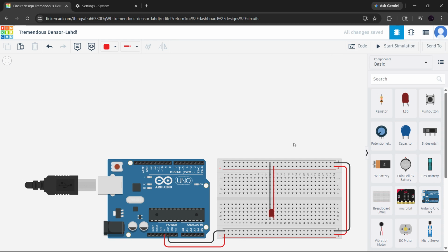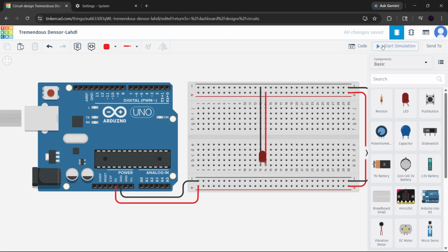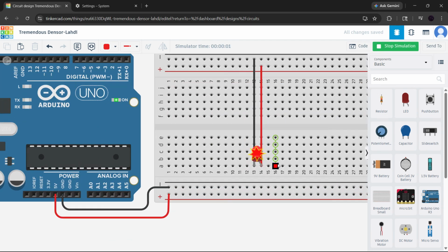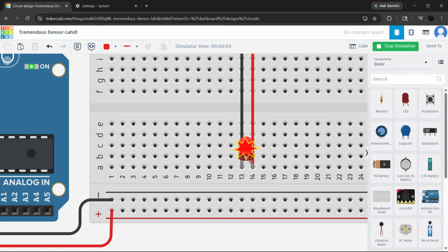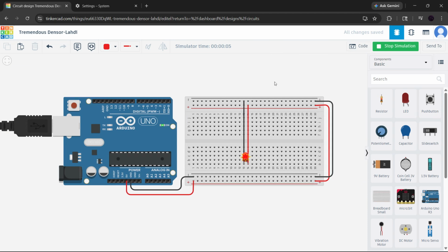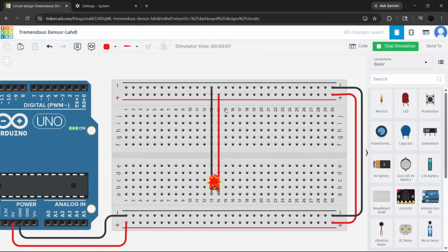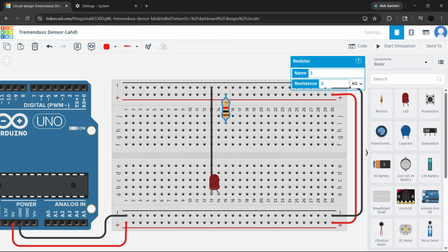This is a big one because sometimes the circuit looks correct, but one wrong value can cause the whole simulation to fail. Start with your resistors. Make sure they are not set to 0 ohms because that can act like a direct wire and create a short. On the other hand, if the value is absurdly high, like 1 gigaohm, your circuit may not function properly either.